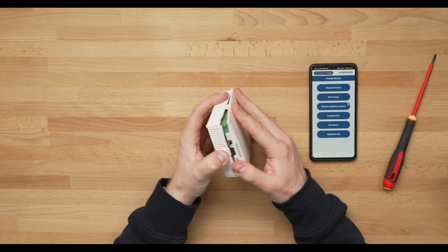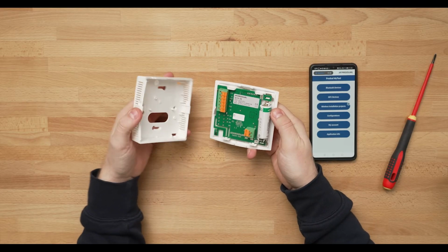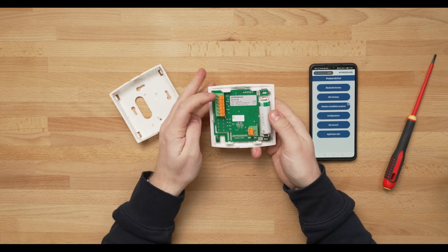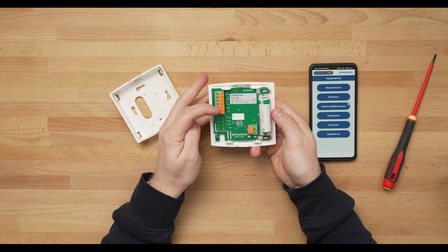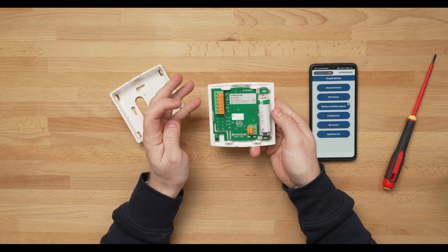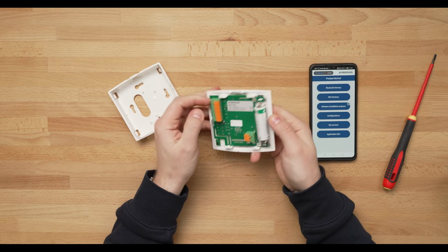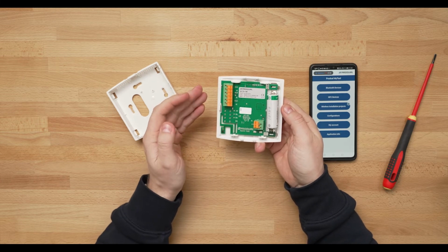Next, we will take a little bit deeper view on the WTR-IM. WTR-IM is an input module for external measurements like NTC10s, digital inputs, resistance, or 0 to 10 volt. WTR-IM has 3 inputs where we can put these external measurements. We have spring-loaded connectors for easy installation.